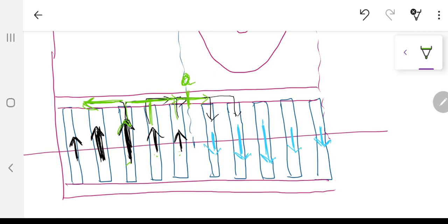Assuming the resistance is equally bifurcated in this whole thing, 2.5 bars are putting the current at this point A. So the end rings are going to have the maximum current at point A. If I take this point as B in the end ring, at point B, because half of the current is flowing towards A and half is flowing towards the other side, and they are going to match up from this side, the value of current at point B is 0.